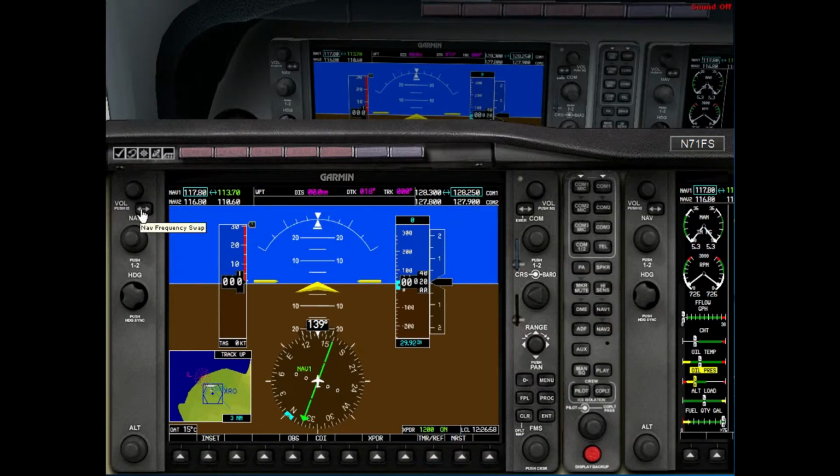And we change from standby to the current frequency set. And we already have our X-ray Romeo Oscar. It's set. And then we can change here if you want to choose the radio you want to depart from, or the radio we are at right now. You can use this to fly and to experience an IFR flight using the VOR only.